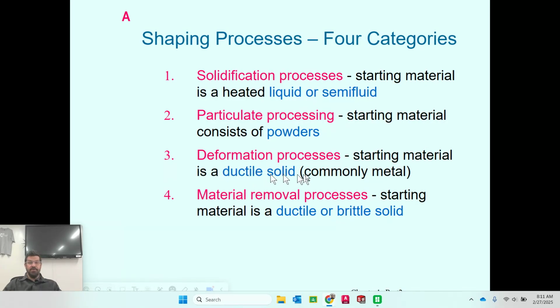In this case, it almost always has to be a metal that is ductile. So a ductile metal, some people in different countries pronounce it a different way. Ductility is the property of a material that allows you to press or bang on one part and it changes shape without shattering. So like glass is not ductile, right? If you bang on a piece of glass, it'll break. But if you bang on a piece of metal, it'll dent. So ductile means dentable, basically.